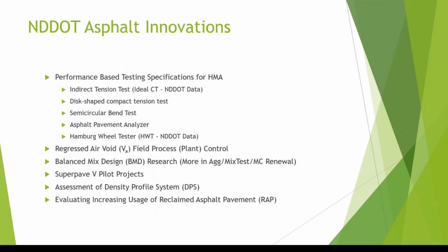The DOT has pulled the retained samples from a number of jobs 2 years ago, basically from every job, and last year from specific jobs in each district, but splitting that into 3 samples per project, one in the first third of production, one in the middle third, one in the last third, so that you get an idea of what's happening to the mix and the performance of that mix from a testing standpoint during the course of production of a larger ton project.